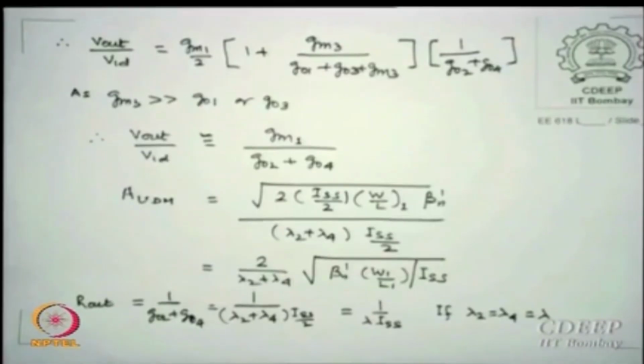Also in many cases in books, we should know this, the voltage gains will be specified as voltage by voltage, though it does not mean, because it essentially is trying to tell that both dimensions are the same, but it is written V by V. Why? Because it is trying to show you it is a voltage amplifier, is that correct? So you should also imbibe this, because there are 4 kinds of amplifiers which we can use, all of you have gone through this earlier: input voltage output current, input current output voltage, input voltage output voltage, input current output current. So it is called transconductance, transresistance, current amplifier, voltage amplifier, all 4.